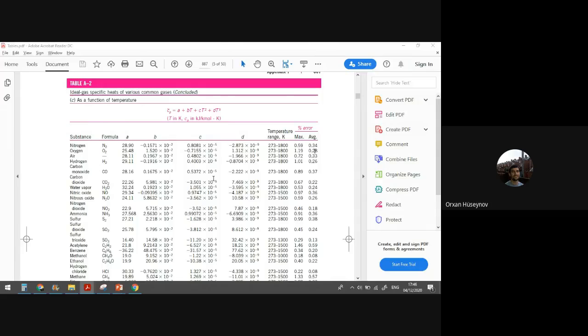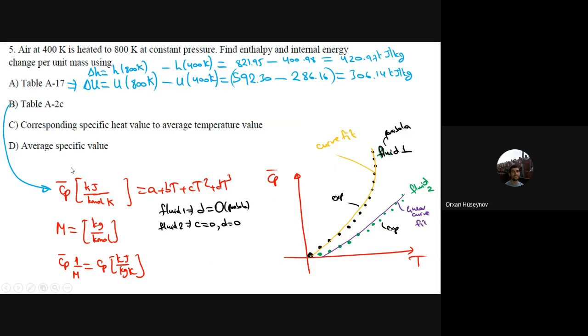Good. Now what I will do is find, since the table only gives the enthalpy, therefore I cannot find the internal energy. So I will say that dH bar is equal to Cp bar into dT. H bar means that it is per unit mole. This one means kilojoules per kilomole, or joules per kilomole.